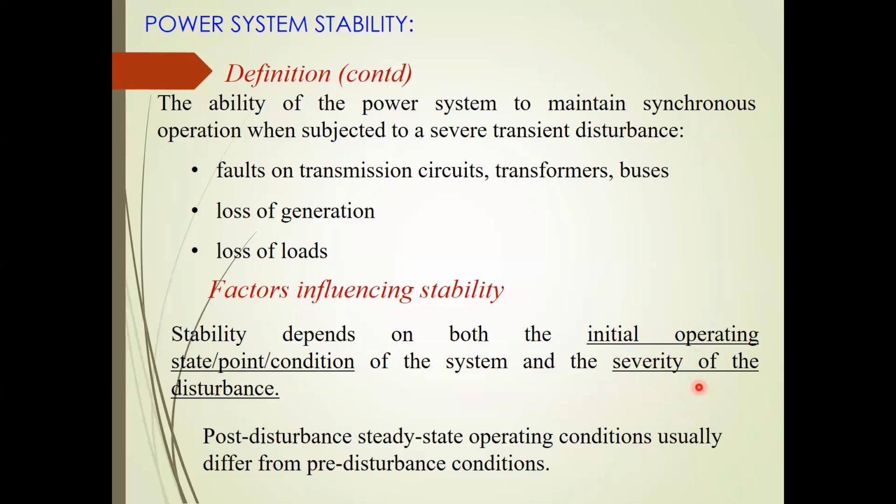You can increase or decrease in 1 hour or 2 hours. But if you have a large change in the load, and suddenly, let's say at t equal to 0+, at this second, a 50% increase in the load is demanded, then all the generators connected in the system will not be able to meet the sudden demand, and there the condition of inequilibrium will arise, obviously.